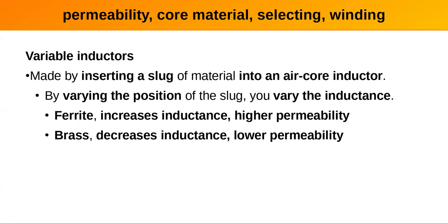And one of the tricks when you're trying to tune filters, you've got multiple coils. They sell these little sticks where you've got a piece of ferrite or iron on one end and a piece of brass on the other end, and you can stick one end or the other in the coil and see how it changes to see whether you need to increase or decrease, because you look at the overall pattern. It's a whole lot easier than trying to disconnect it, take a turn off, put a turn on, resolder it.